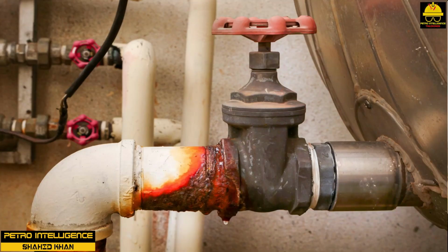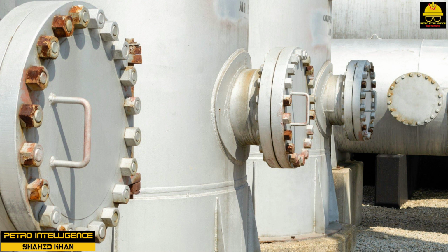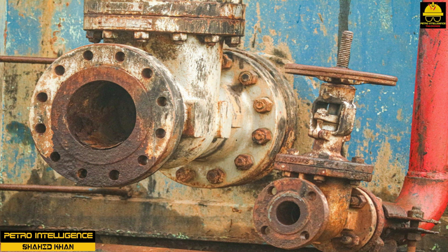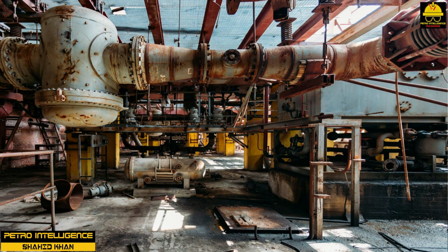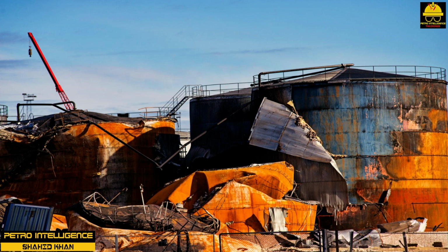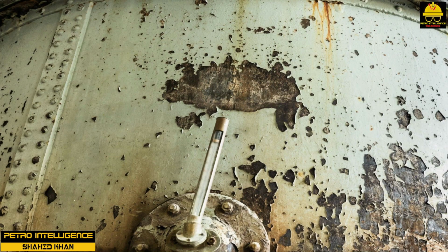Corrosion. Corrosion is described as an electrochemical reaction between metal surfaces and fluids that results in the gradual wearing away of the metal. In addition to strength requirements, equipment design also takes into consideration corrosion, that is, metal loss. Knowledge of prior experience under closely related environmental conditions is necessary in order to establish the amount of corrosion that can be expected. Where severe corrosion is not anticipated, 1/8 inch of extra metal is added.